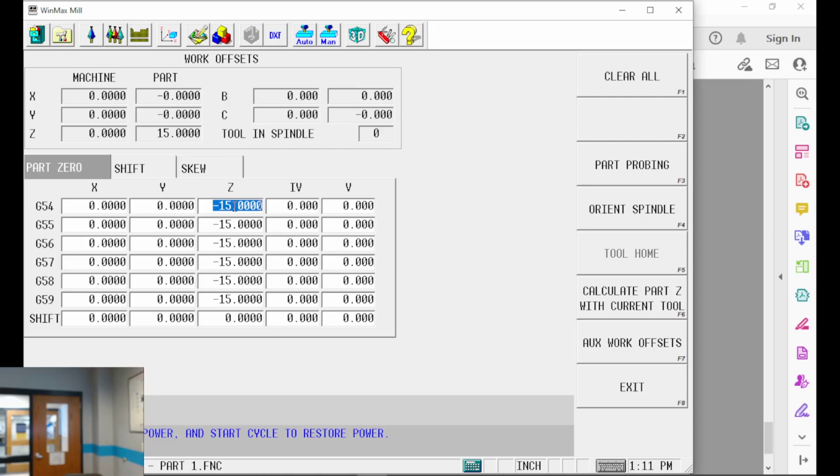And that's all we're doing, we're setting it up for our NC state, making the computer think that you're actually at a machine and there's actually a gap between the tip of the tool and the part when we start out. If we don't put those in there, and we forgot yesterday, everybody in the class went, because when we drew the part the first time, it had a hole in the part where it was just supposed to have a spot drill, because it thought the tool was sticking through the part already, 5 inches long, right? And it thought we were at 0, and it thought 5 inches of the tool was sticking, and then it had to go up from there. Freaked everybody out a little bit, but it was because we forgot to put that number in there.